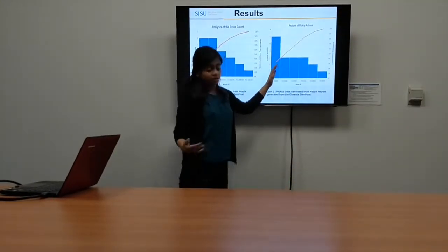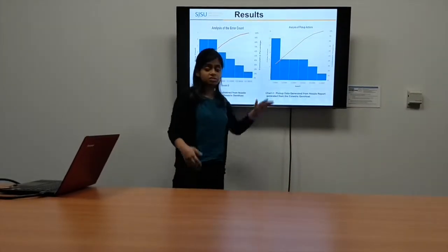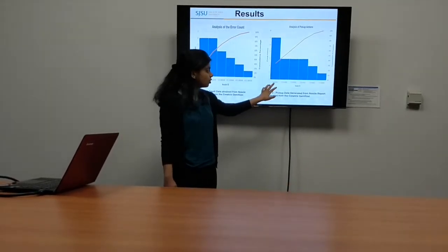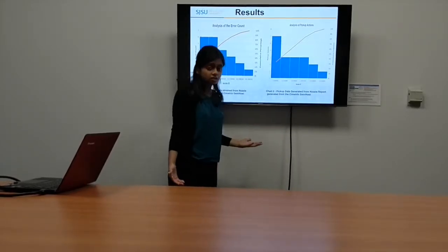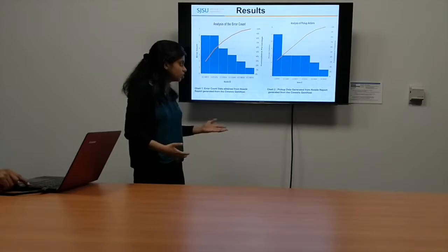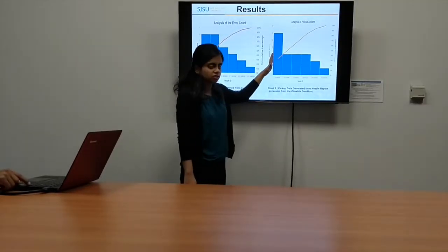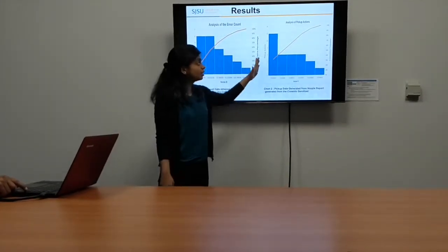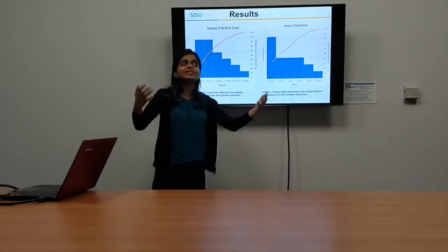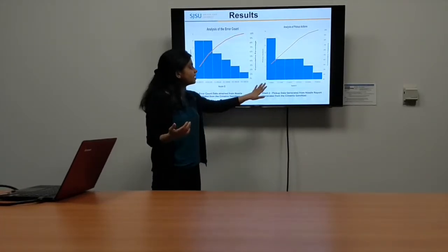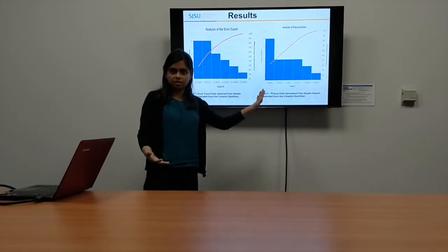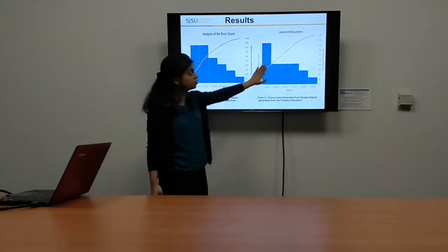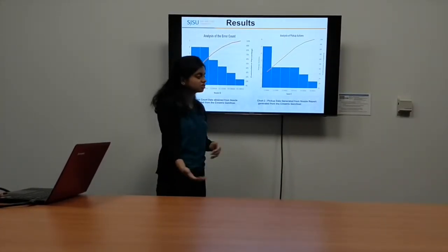On the other hand, one of the positive things that you can evaluate is which nozzle was performing the best. While evaluating different nozzles, we found out that the T113-05630 nozzle ID had the highest pickup actions. If something is going right this way, you can go back to the production data that you're receiving in real time using SEMI GEM and see what's so good about that part and why the other nozzle parts are underperforming compared to this one. So there can be a lot of analysis going on this way.